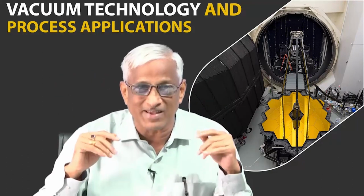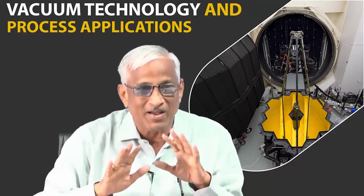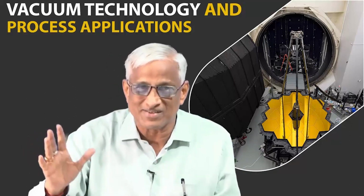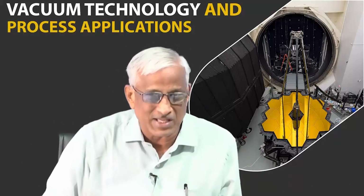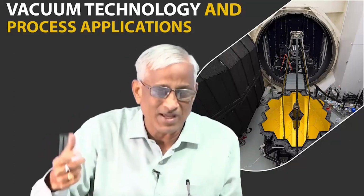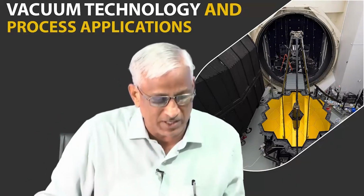So, depending on the application, you have to choose the material, but finally it is only a 1 bar pressure difference, not much. So, mechanically, if you make that design following ASME codes for an external pressure vessel with 1 bar atmospheric change, it is good enough. And if you want to reduce the thickness, use stiffeners outside.